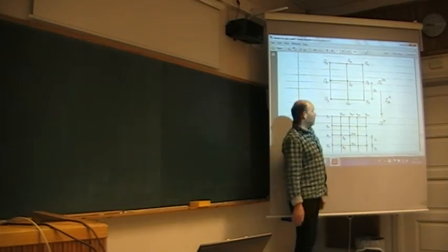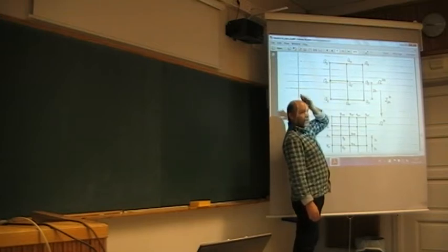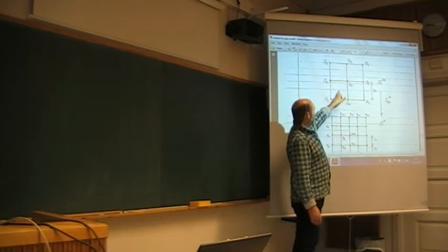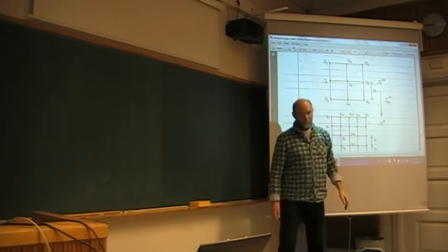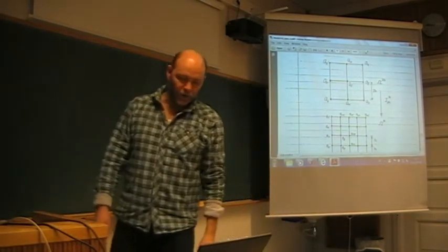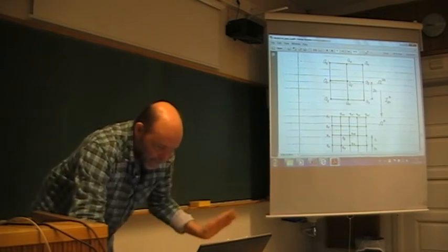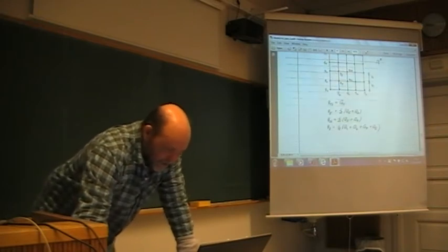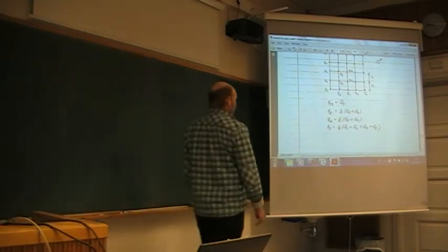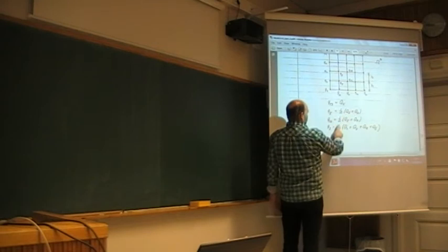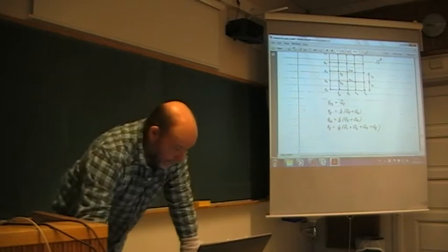So it depends on your layout. I'll show you later when I did this with the SIMPLE algorithm for the pressure. Well, the pressure is located in the cell centers. Then it will be totally different. So it's just a matter of bookkeeping, of course, but you have to know what you're doing here. And here everything was stored in the corner, so you have some operators here where some will be the direct points, some will be an average between 2, and some will be an average of 4. Pure geometry, so it's not that difficult.